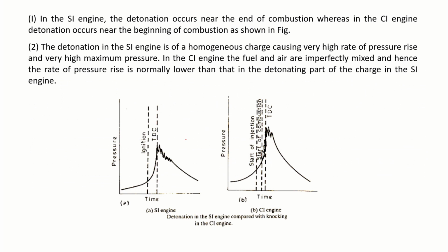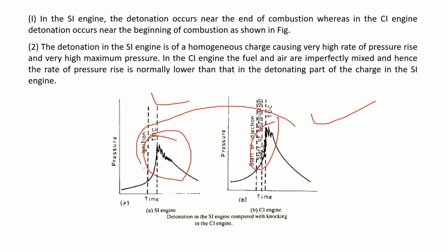The difference between petrol knock and diesel knock is that petrol knock happens because of shorter ignition lag. It happens at the end of combustion, during the third phase, the afterburning stage. In a diesel engine, if I maintain a larger ignition delay, knock happens in the beginning of the combustion itself. Anyway, by introducing electronics, that is common rail injection, an engine management system and petrol injection, we are smoothing out all these things and improving the combustion processes.